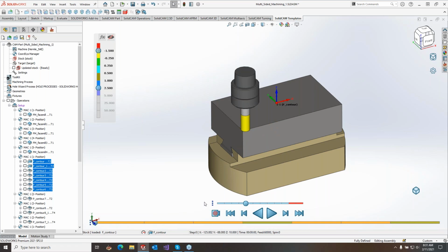Now I will turn off the simulation or the recording, and I will click the menu because I want to bring up that there's two modes to simulating in the new simulator. There is a performance mode, which is what we're using currently, and this is similar to the existing simulation that we have in SolidCAM. Basically, this is playing toolpath point by toolpath point, and it's either playing as fast as the CPU can when it's at the highest points, or we add a slight delay to make an animation feel to it. We have machining time mode.